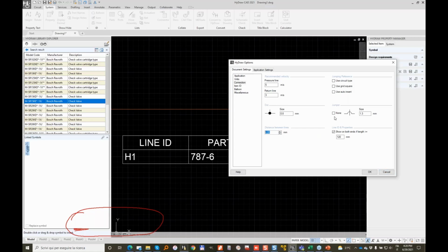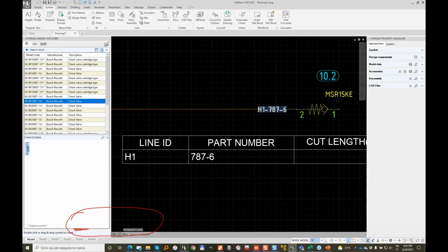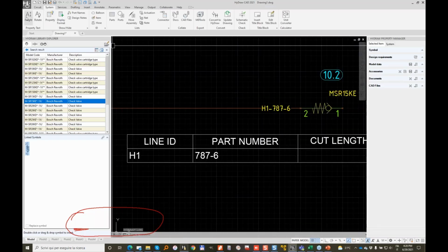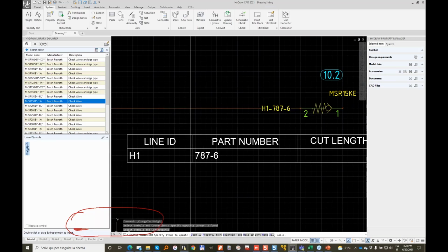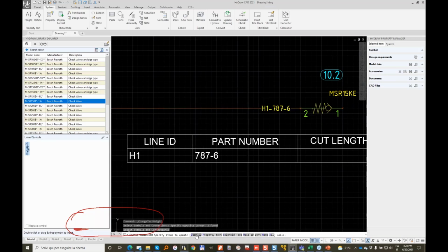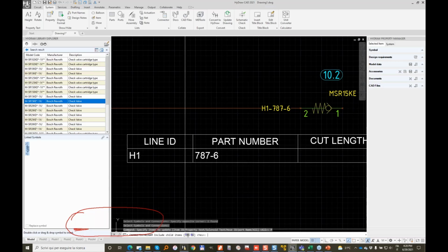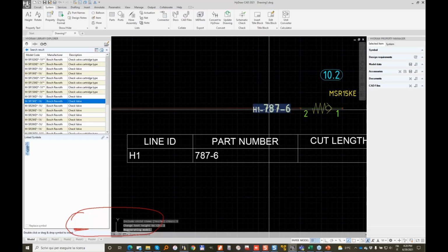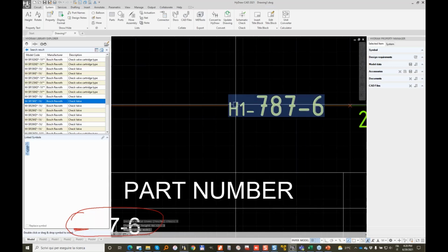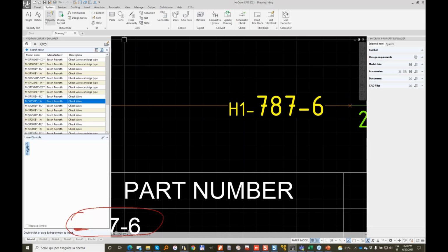If you need to change text height on a drawing, you just can run height. You select the entity that you need, and you can change the property text and make it 3 mm, and that will change the property text. So in this case, it's the ID, it's not the property text, it's the ID. Let me do again.